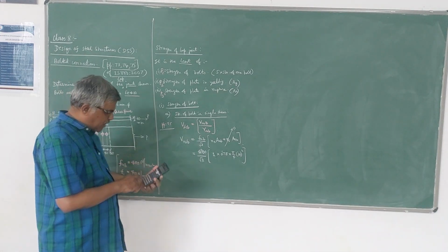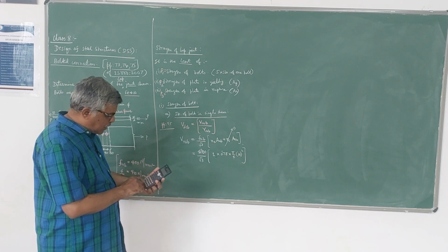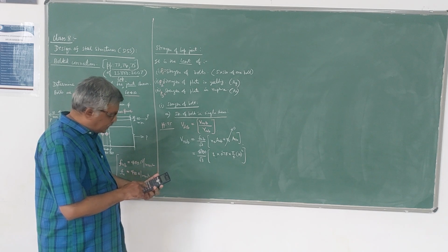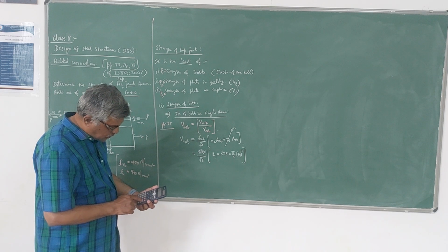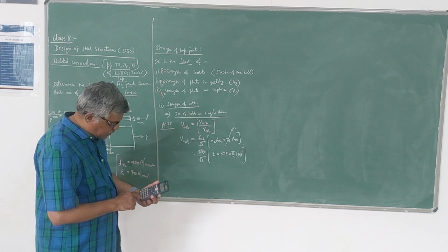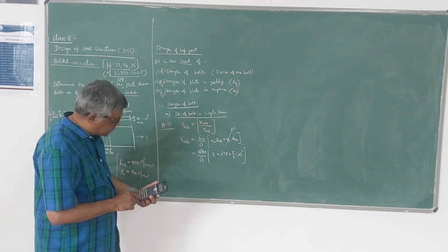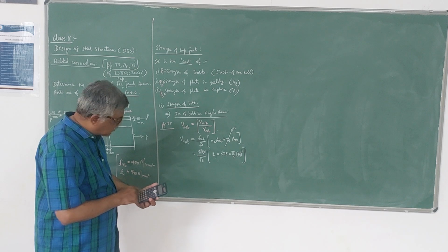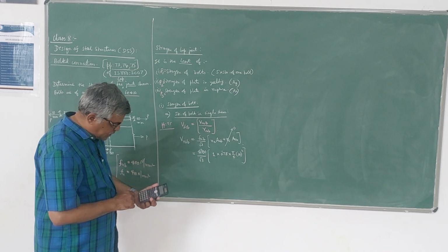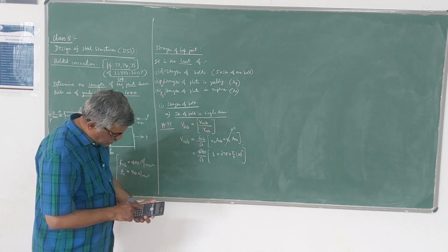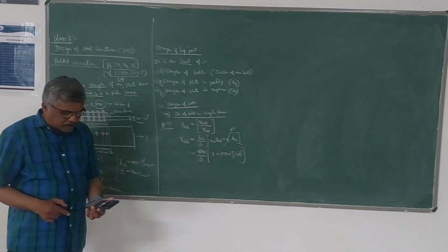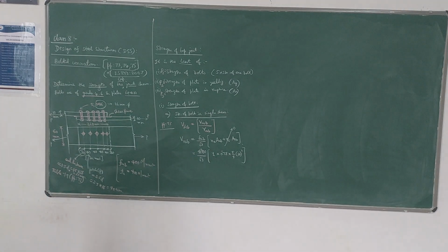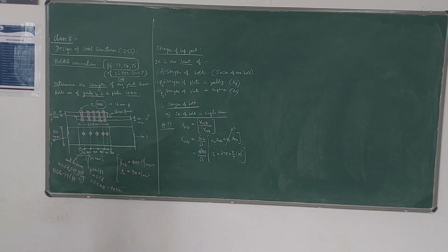If you simplify this term, you will get 0.78 into pi divided by 4 into 16 square, that is 256, into 400 divided by root 3. So we are going to get the value as 36.22 kilonewton. Of course, that is what you are getting: 36,217.9.